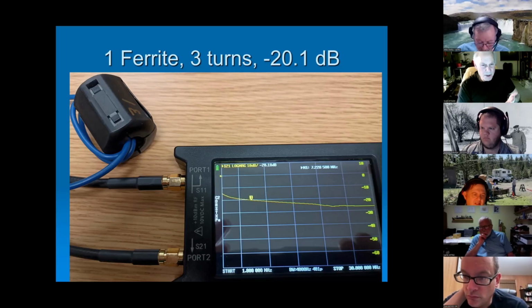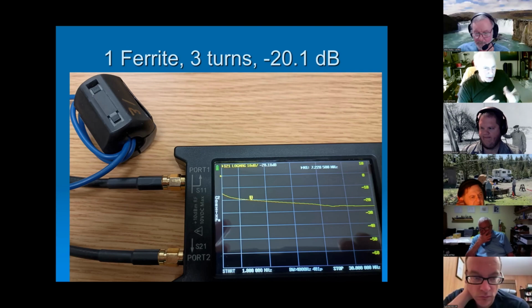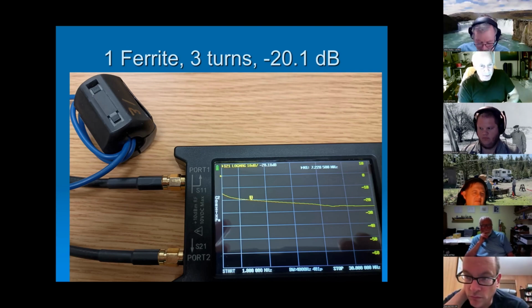The real component is related to the inductance, the magnetic effects, and the imaginary component is related to loss effects. Absorption, and then the energy being used up, trying to make the molecules not vibrate but move, and heating up the core. For most RFI and EMI, they choose the material based on that effect, not the inductive reactance effect.